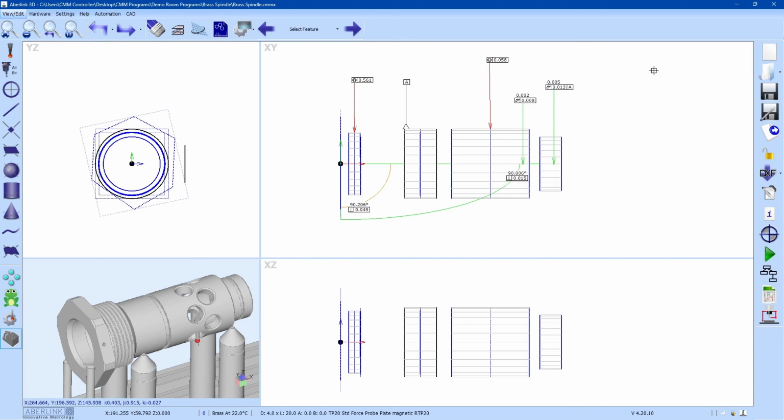Now, if you don't see any datums on your drawings, that will be a big red flag, because that is defining no dimensional order, and it's a bit of a free-for-all, completely up to you which ones you pick. So designers should always implement a datum call out on any runout, circular runout, or concentricity checks, and that dictates that you click on the datum first to do the alignment of the dimension. So that wraps up this series. Thank you very much.